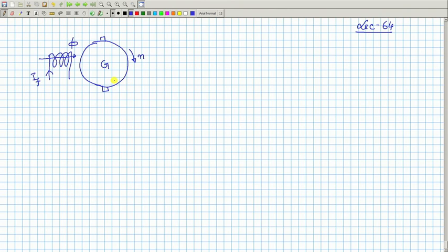So, what I am trying to tell in this schematic diagram, you must try to understand that whatever is happening in the armature conductors under a pair of poles, the same thing is going to happen to other armature conductors under the next pair of poles. So, people represent this simplified diagram pretending it is a two pole machine. If you know what is happening under a pair of poles, the same thing will happen. So, that is why it is done like a two pole machine, north pole, south pole, a pair of poles. This is 180 degrees electrical and so on.